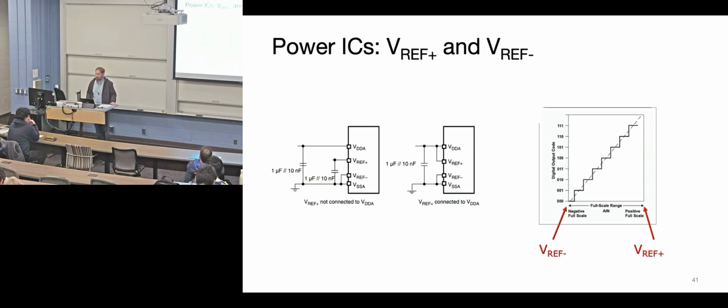I just wanted to clarify on this. Your reference voltage can be anything you want, pretty much. If you know the signal you're going to be sampling doesn't go past 3 volts, you can make your reference voltage 3 volts. Conceptually, yes, for this magical ADC or DAC that we've been talking about.